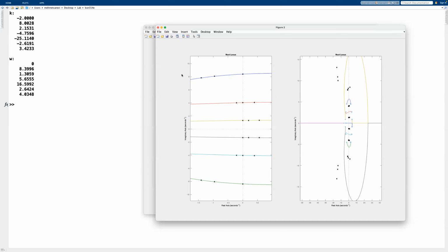You should do the same with the Padé approximation. Never, ever, ever use the Padé approximation transfer function in any Simulink or in any step response or linear simulation command whatsoever, because it doesn't exist. There's no system that is the Padé approximation itself, because it's an imaginary representation that is a transfer function, and that is all it is. You will use that for stability analysis. You will use that for controller synthesis. You will use it for all kinds of things except simulation. So applying a step to this Padé approximation doesn't make sense.